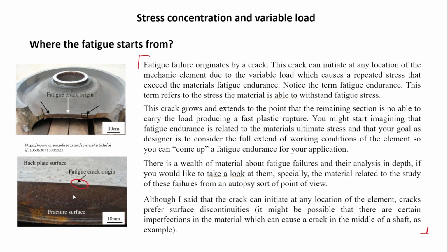And also that's tightly related to the manufacturing process of the material, because imagine at this point you have certain pores or empty voids here that shouldn't be there, but appear because of the poor quality control during the manufacturing process. Then you can have something here that is going to increase the stresses in that area, and then everything can originate from that.